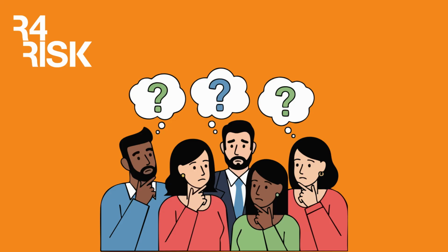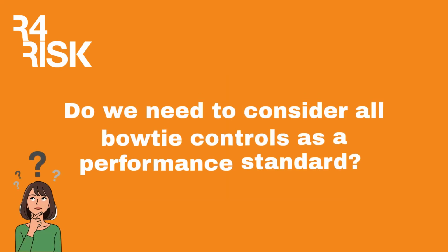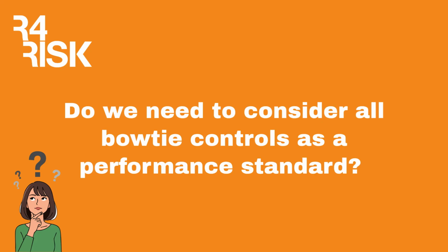So other questions are, do we need to consider all bow tie controls as a performance standard? Not necessarily. You don't need an individual performance standard for each individual control. I would say that you can have overarching performance standards for groups of controls, or really it's your safety management system elements.